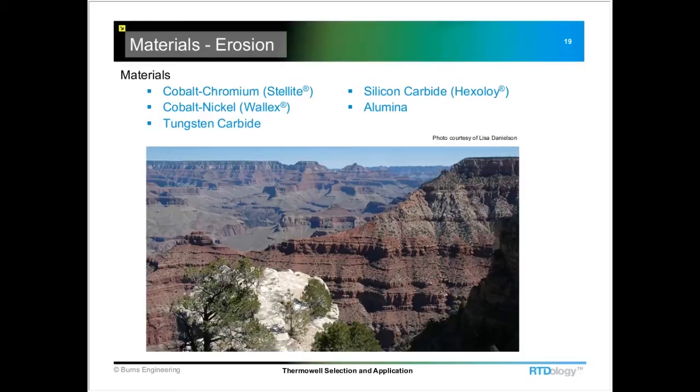It wasn't the right temperature reading, but it was still working, which really surprised me. There was enough of this material going by to actually deform the thermocouple conductors so that they were still touching each other and still giving some sort of a temperature reading. But the solution there was to supply a Thermowell with a stellite coating on it, and that solved their erosion problem.